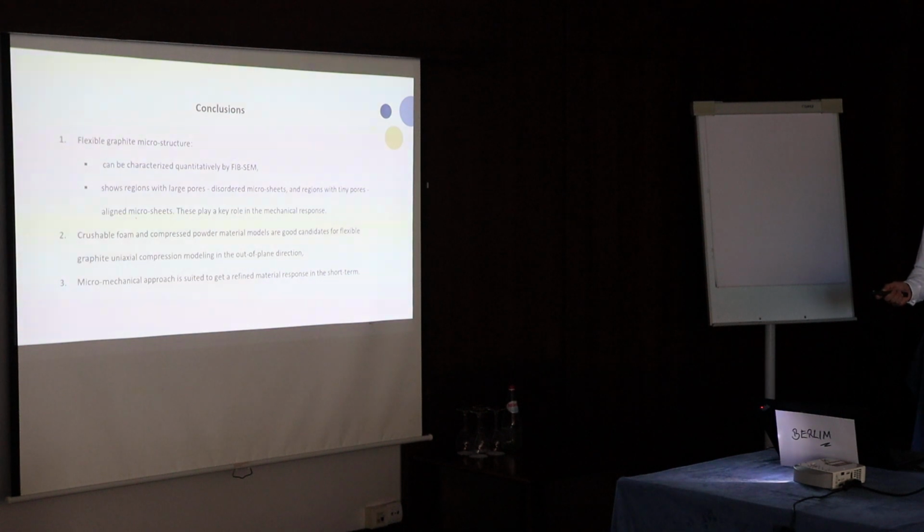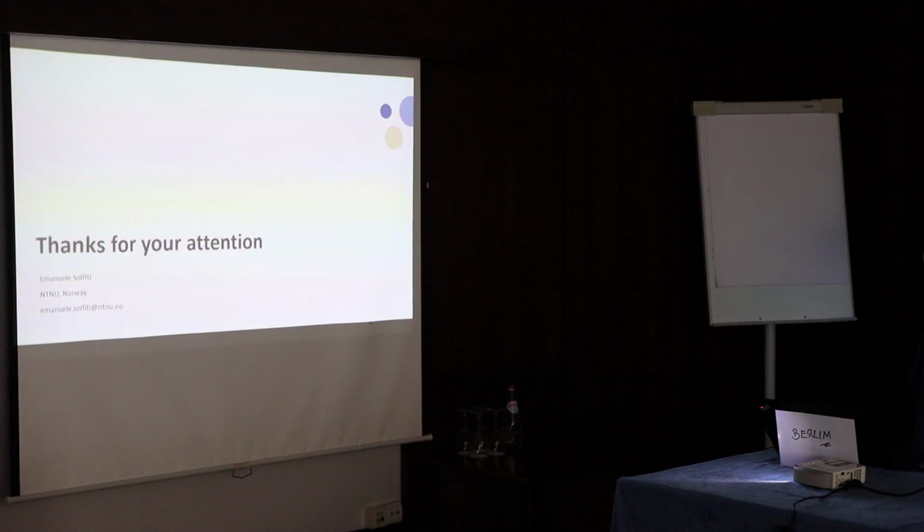The overall mechanical response itself is probably similar to a crushable foam or a compressed powder, at least under these conditions: static uniaxial compression out of plane. But probably we need a more refined description of the response, a micromechanical approach, also based on this kind of imaging technique. With this, I conclude my presentation, and thanks for your attention.